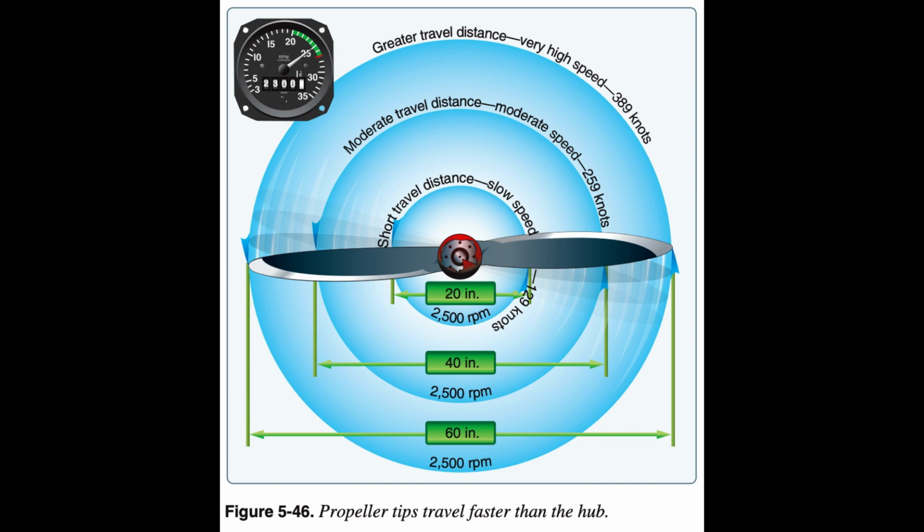Usually 1 degree to 4 degrees provides the most efficient lift/drag ratio, but in flight the propeller AOA of a fixed-pitch propeller varies, normally from 0 degrees to 15 degrees. This variation is caused by changes in the relative airstream, which in turn results from changes in aircraft speed. Thus, propeller AOA is the product of two motions: propeller rotation about its axis and its forward motion. A constant speed propeller automatically keeps the blade angle adjusted for maximum efficiency for most conditions encountered in flight.